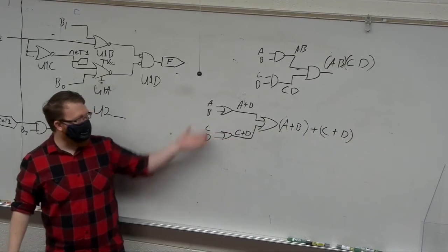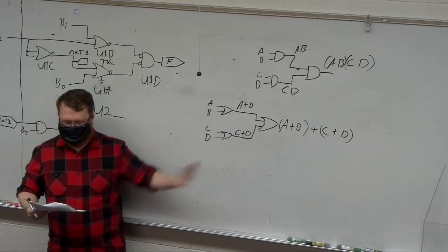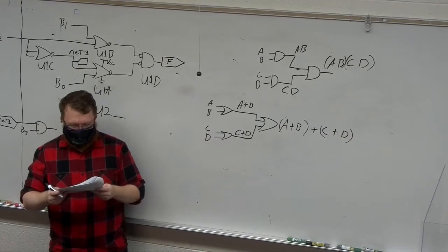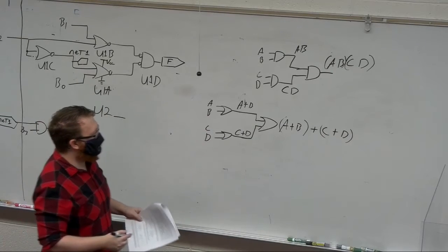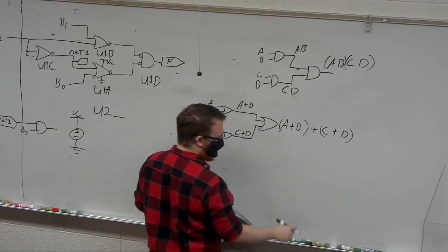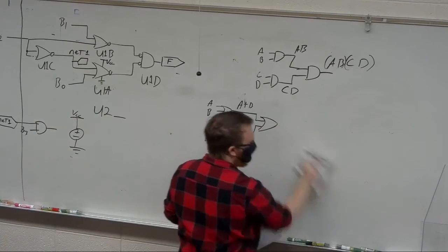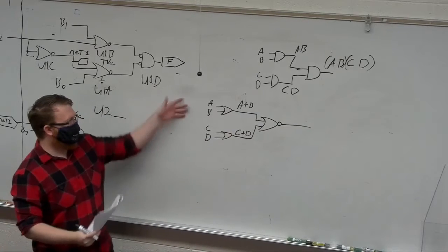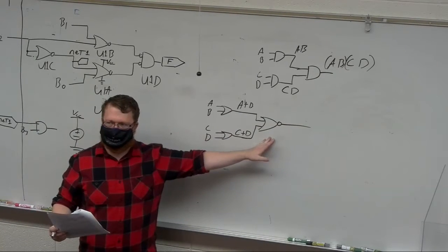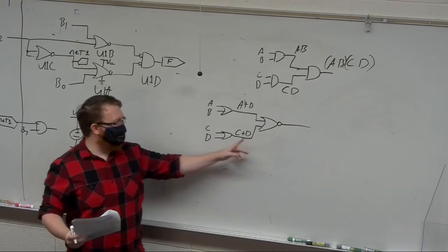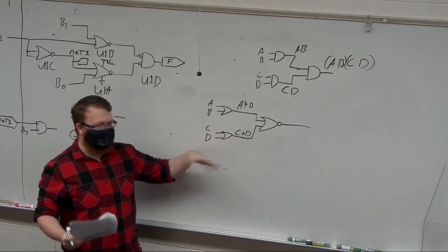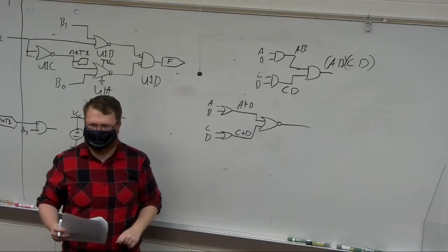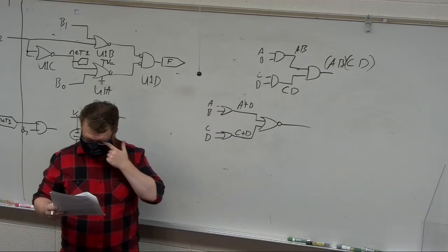So that this is a 4 input OR gate from just 2 input OR gates. To do a 4 input NOR gate, it's just that. I take 2 ORs, throw it on a NOR. The challenge then is if you only have NORs and inverters, you may need to do NOR, NOR, invert, invert, NOR, right? Obnoxious, but doable.